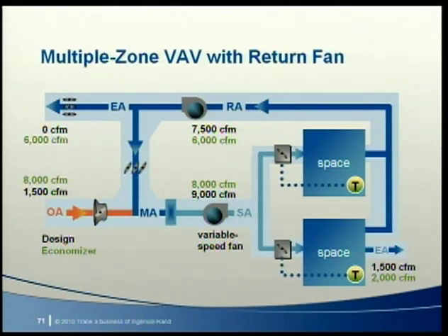Since the outdoor air damper is closed, the supply and return fans are in series. Both fans handle the same airflow, which must be high enough for the heat exchanger, but not too high for the fans selected. In quick summary, if the return fan is selected for a design airflow of 7,500 CFM, then the supply fan flow probably needs to be controlled during morning warm-up to limit its airflow to 7,500 too.